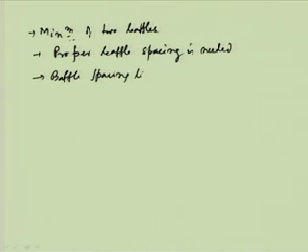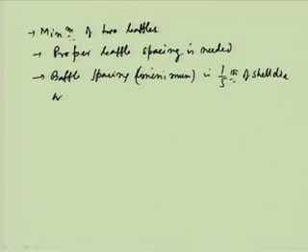Usually the minimum baffle spacing is 1/5 of the shell diameter or 5 centimeter, whichever is larger.